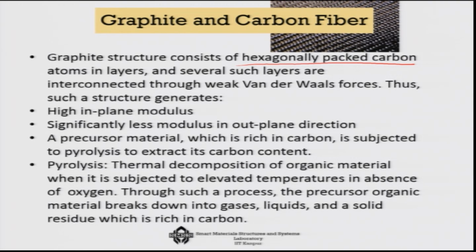So, that layered plate-like structure, in plane it has tremendous strength, but it is interconnected through weak van der Waals forces. Such a structure will give you high in-plane modulus and less modulus in out-of-plane direction. A precursor material which is rich in carbon is subjected to a high temperature, which is called pyrolysis, which is a thermal decomposition of organic material when it is subjected to elevated temperature in absence of oxygen. That is the pyrolysis process. So, using the pyrolysis process, one actually carries out this kind of graphitization of a system.